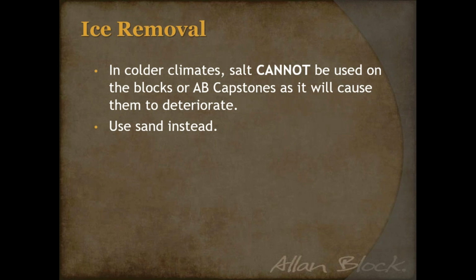I know a lot of contractors, as they're working with homeowners, leave that text sheet with them as part of that final walkthrough and final blessing, because it talks about keeping it clean, pulling a weed once in a while, and it really specifically talks about salt use around pavers and retaining walls. So use that for future use and try to make sure you don't have the problems that might be associated with salts deteriorating concrete over time.